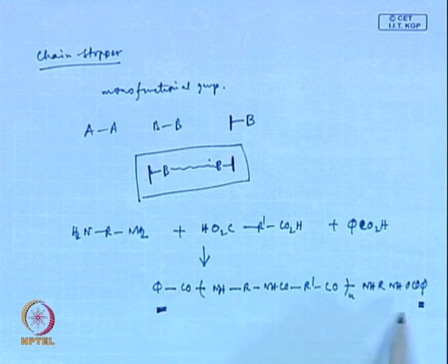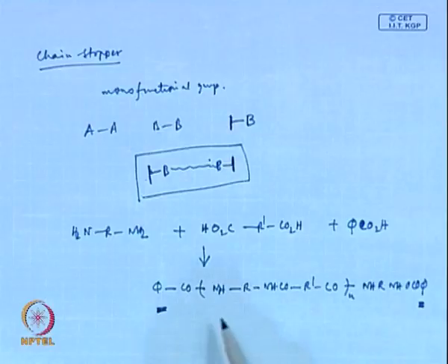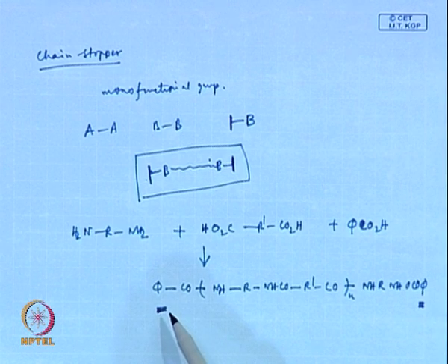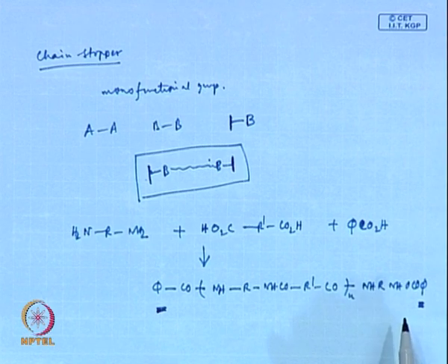So, if you take this polymer out and do further molding and compounding, go to the compounding step, then because these chains are capped with a non-reactive group, they will not take part in the reaction, which means your polymers are practically dead polymers. So, your molecular weight will not change. At the end of your processing steps, you will get the same polymer, with the property related to your target molecular weight.